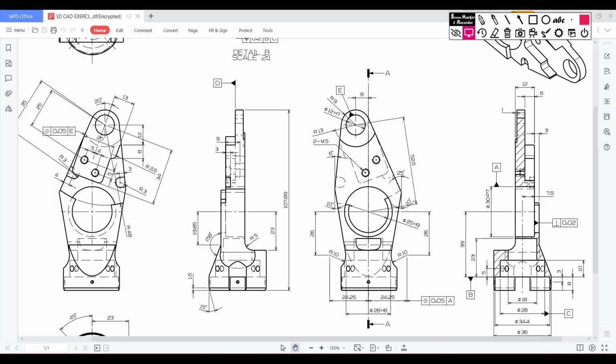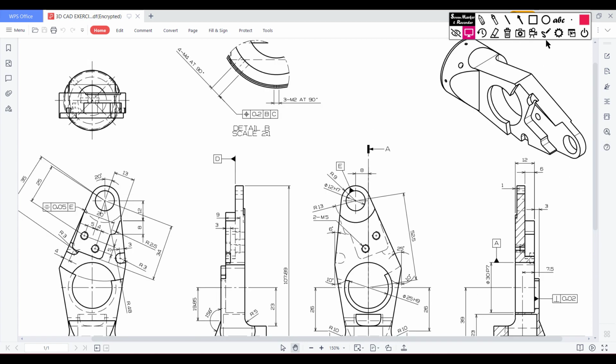Now again go to our sketch, and in our sketch we can see in this back portion we have an extrude cut of 1 unit, and this extrude cut circle has a dimension of 13 radius. So in this back portion I will draw a 13 radius circle, then I will cut it to 1 unit.